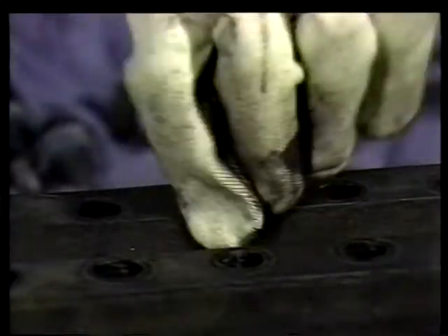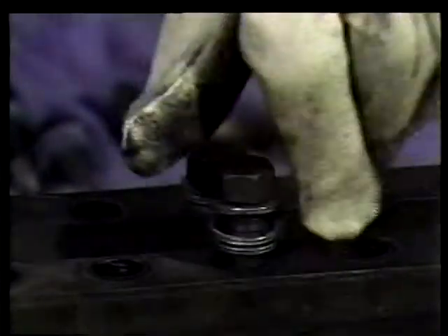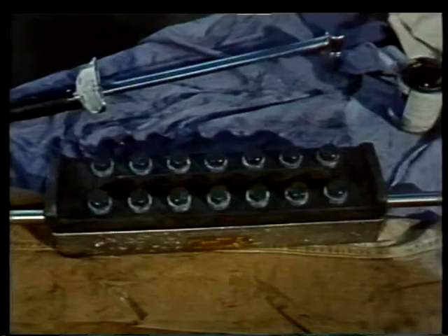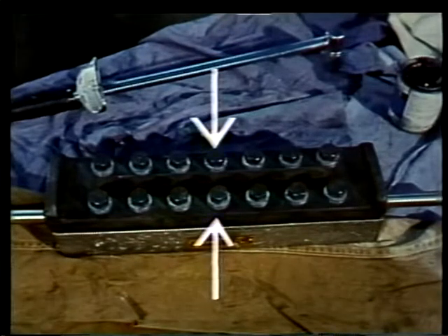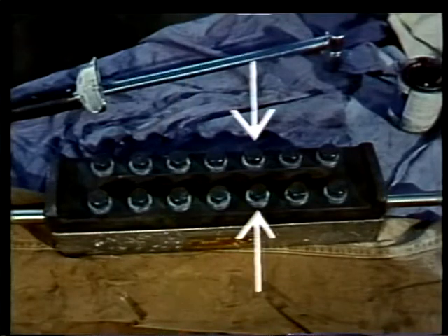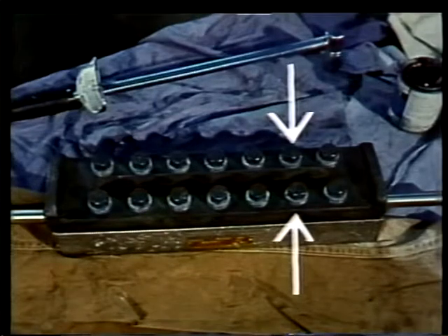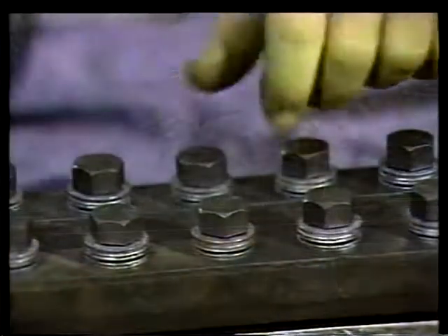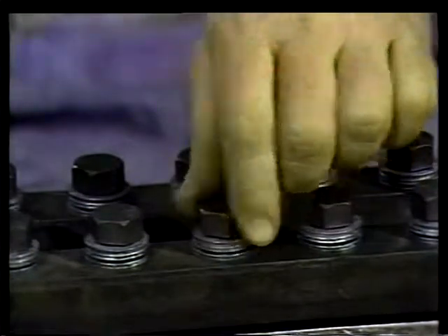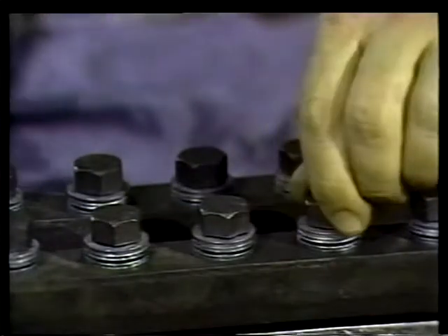If you have any question about how to put back the spring washers, check the manufacturer's instructions or ask your supervisor. Turn the bolts hand tight in reverse order of how they were loosened. Start at the middle of the gauge and work outward so the cover will be drawn down evenly. All manufacturers will have their own methods of tightening bolts, but this is the typical way of doing it. Hand tighten the bolts a second time, again starting in the middle of the gauge and working out.